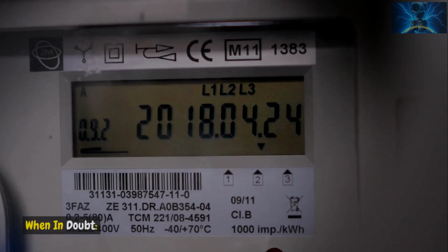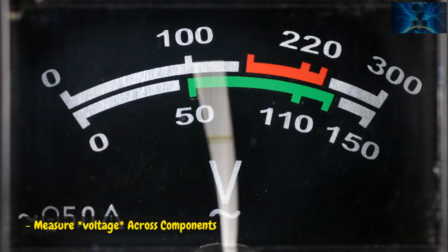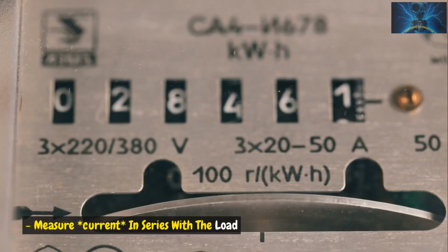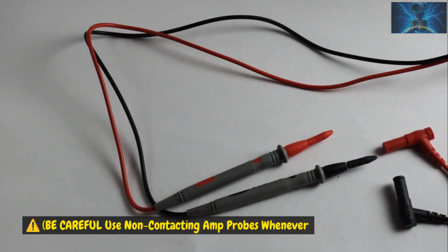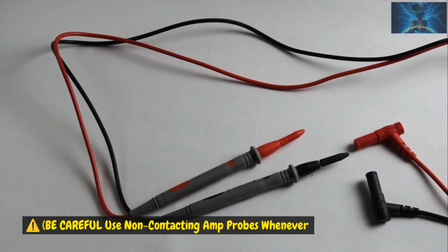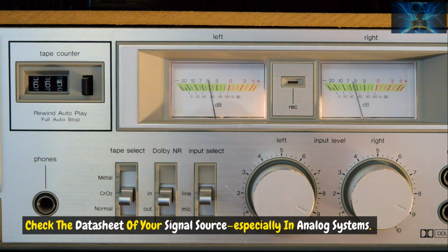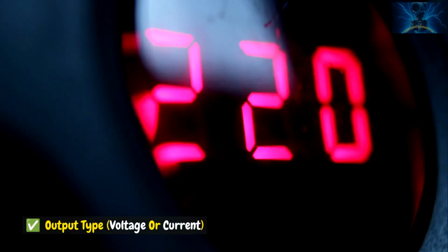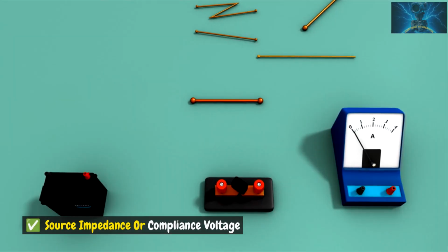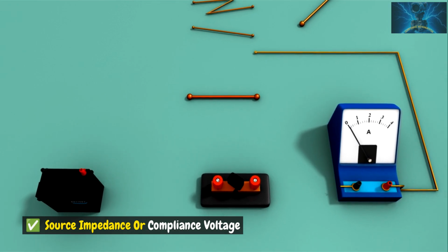Quick tech tip: when in doubt, measure voltage across components. Measure current in series with the load. Be careful. Use non-contacting amp probes whenever possible. Check the datasheet of your signal source, especially in analog systems. Look for output type, voltage or current, range and limits, source impedance or compliance voltage.